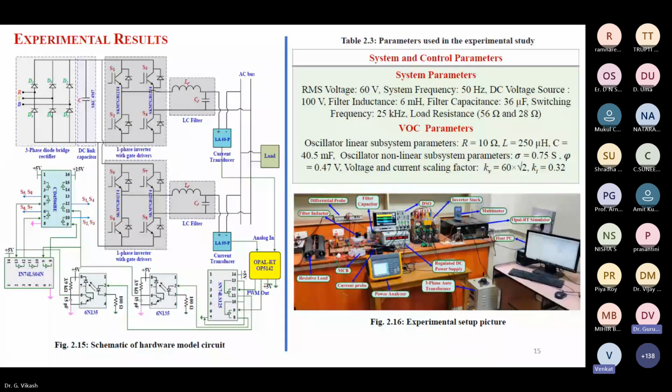If S1 and S2 are short circuited at a time, what will happen? There will be a shoot-through fault. The S1 signal I have, I am just simply inverting. Okay, understood. Thank you, sir. Shall I continue? Yes, continue.